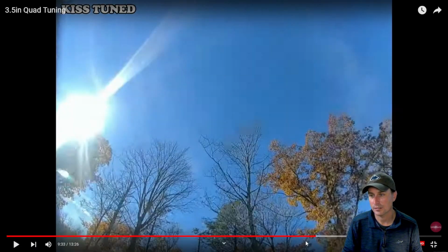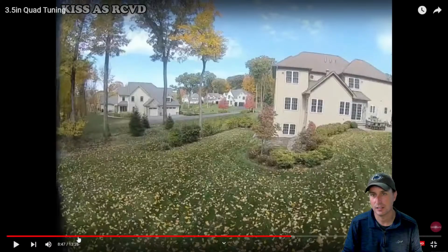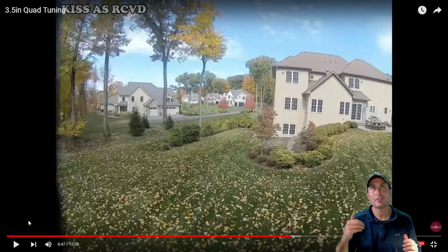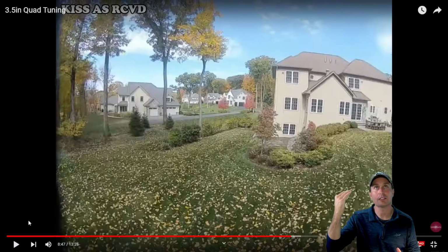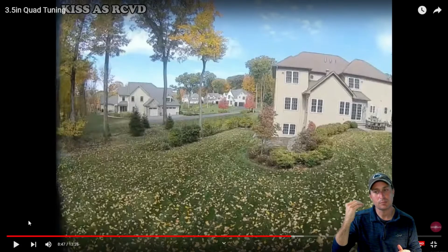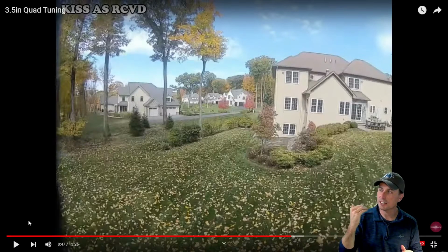Now let's go to, and this is what I was talking about with the KISS. So with the KISS tune, I have D as high as it can go. You can't go any higher in D. It will start to flutter. We're on the edge of the fluttery D thing, so I have it just below that, maybe 1 or 2. I think he started getting flutters at like D of 12. I moved it down to like 11, I think. I think he had it at 10 initially, so I couldn't get any more.